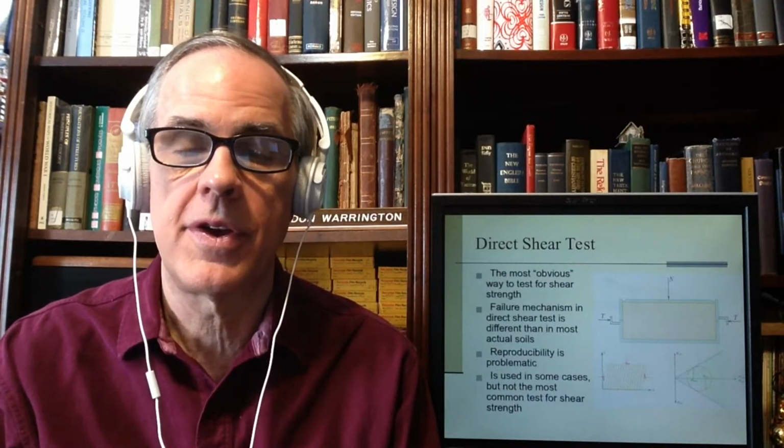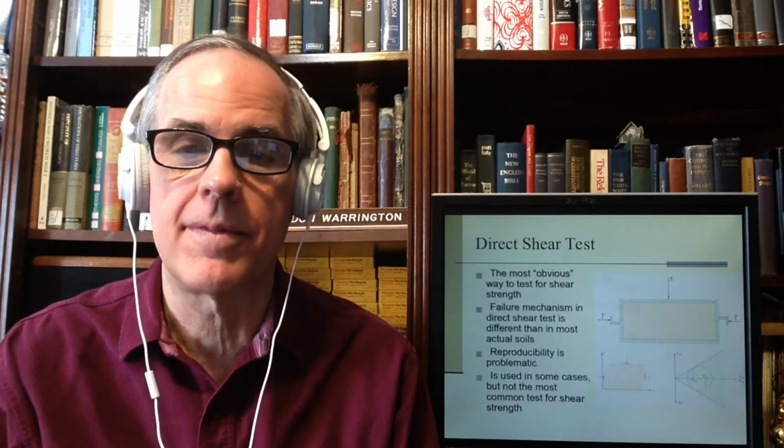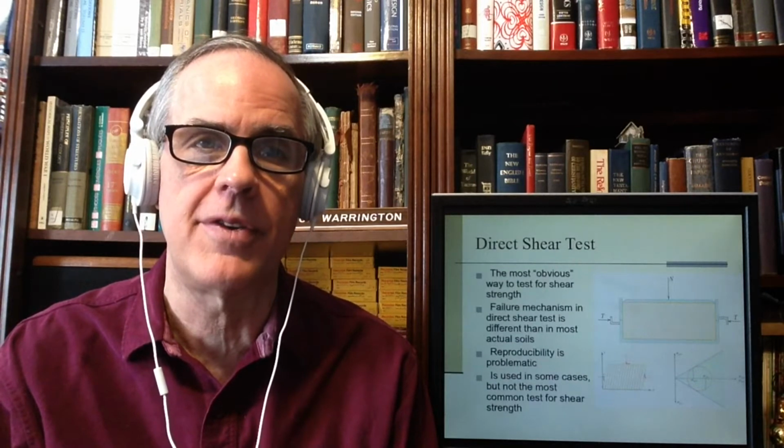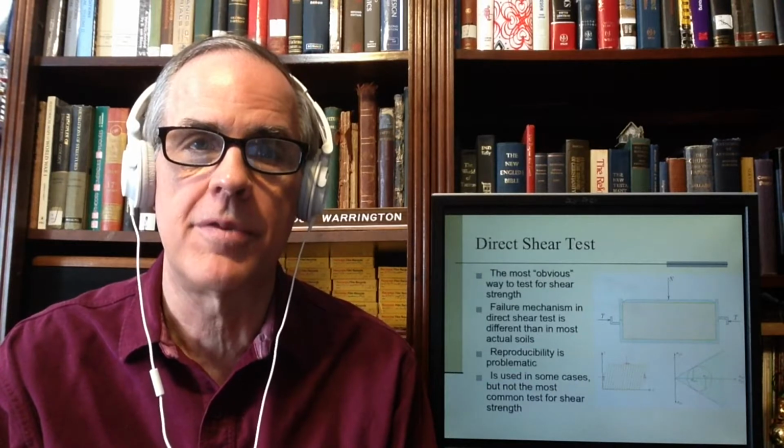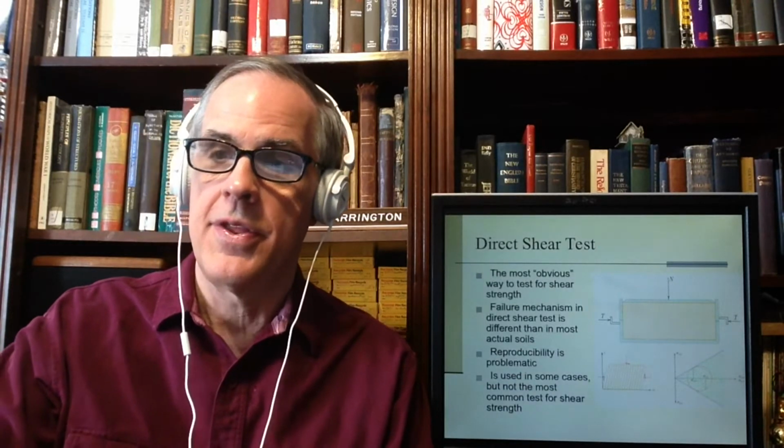The failure is reproducibility is problematic. You see it in some cases, but generally speaking, if direct shear had solved our shear test problems, life would be a lot simpler. The test that is used more often, and I don't want to get too deeply into this because it's easy to get very deep into this test, is the triaxial test.